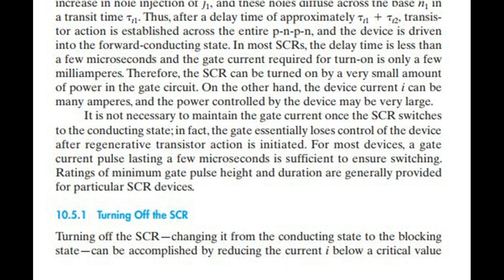In fact, the gate essentially loses control of the device after regenerative transistor action is initiated. For most devices, a gate current pulse lasting a few microseconds is sufficient to ensure switching. Ratings of minimum gate pulse height and duration are generally provided for particular SCR devices.